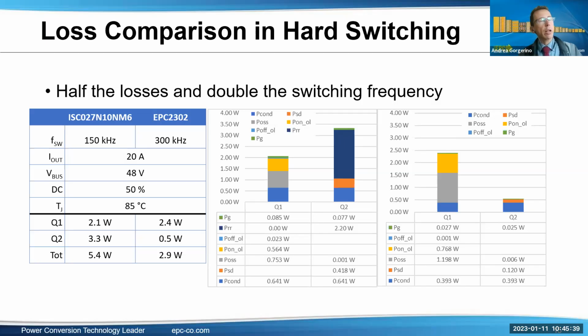I'm wondering if the question means something more like, some of the thermal runaway mechanisms are linked, for example, to RDS(on), right? So in a silicon FET, the RDS(on) increases with temperature, and that's the same mechanism with GaN FETs. I'm not sure about the question actually.